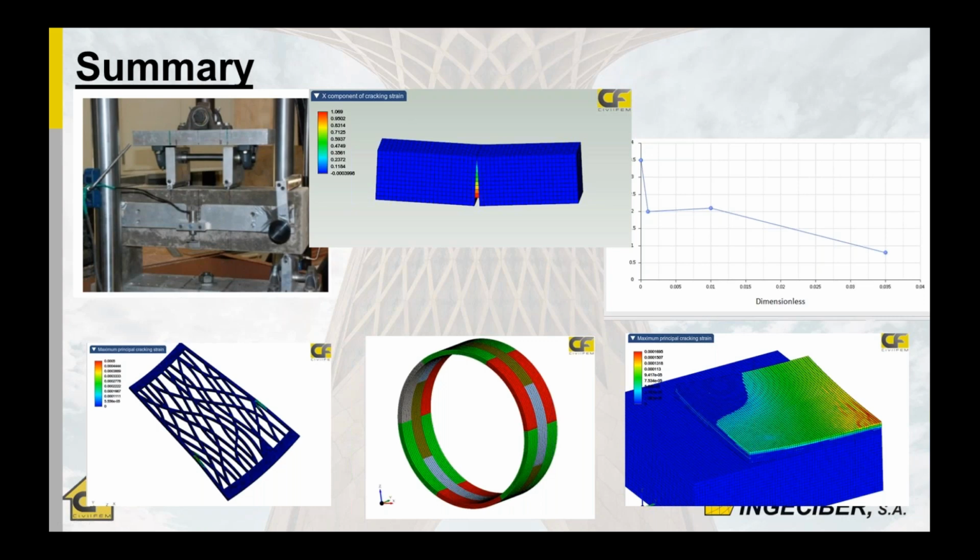The American codes and European codes have different beam tests with different dimensions, with an induced crack here, obtaining the force versus deflection curves to guarantee ductility. The codes also specify some formulas to obtain these stress-strain relationships from the beam test, but we can increase the accuracy of the model by adding extra points, performing a model following this test and adding these points.